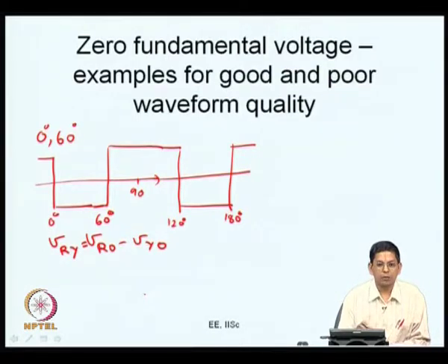So, the third harmonic component: when VRO is phase shifted by 120 degrees, all the triplen harmonics, the third harmonic, ninth harmonic etc. are all shifted by an integral number of cycles. The third harmonic is shifted by 360 degrees at its own frequency. So, when VRO and VYO are subtracted, the resultant waveform has no third harmonic. The resultant waveform will have no ninth harmonic and 15th harmonic etc. So, VRY will be just 0 and it will not have any fifth or seventh or anything like that.